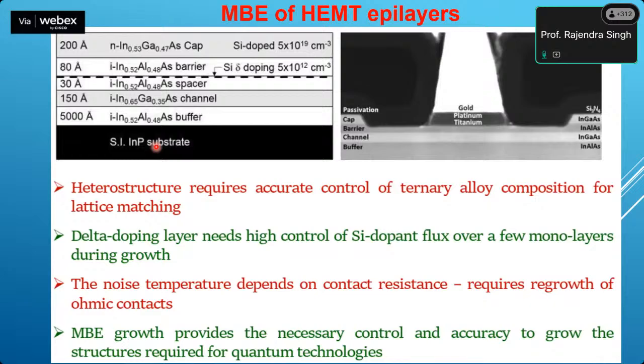So that's why you have to be very careful about the growth of the material, which material you are going to grow on which substrate, and you have to minimize the defects also. If you have a lot of defects, then the device is not going to work. So all these things have been very carefully engineered. One thing is the design, and second thing is, we should be able to deposit also. This is also another thing. You should have the right kind of expertise to deposit, let us say, this much with 500 nanometer, or indium aluminum arsenide spacer with 3 nanometer, so precise, 8 nanometer.